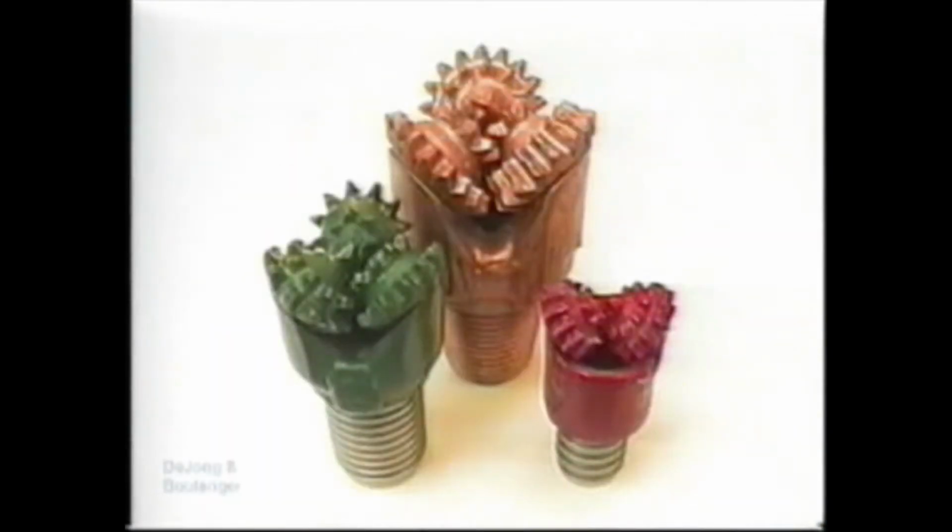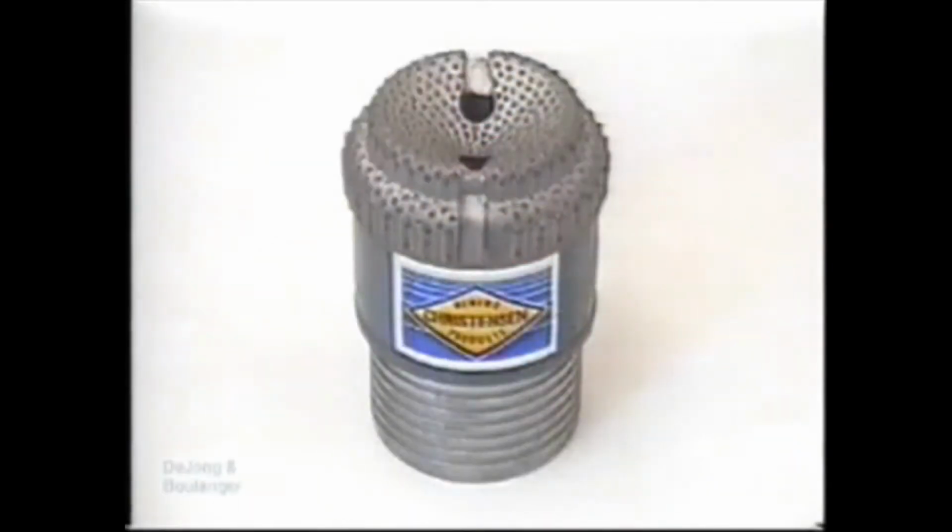The cone bit has teeth on the surfaces of cones, which rotate as the bit is turned. The spacing and size of the teeth on the cone depend on the type of material to be drilled. Plug bits come in 3 basic types: concave, pilot, and tapered. The concave plug bit, pictured here, is designed for drilling through relatively soft rock.